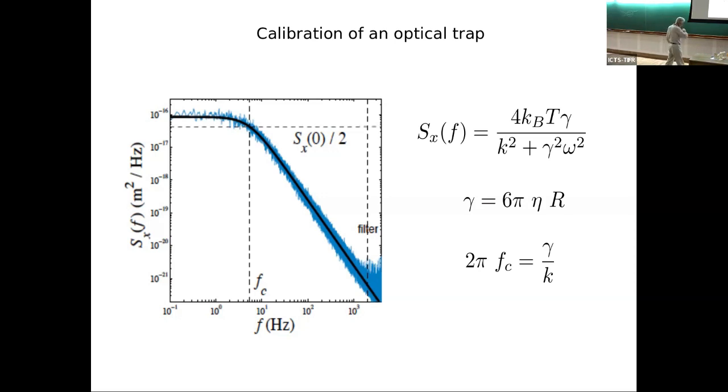This is rather a technical question, but it can be of interest to everybody. We will see in the case of the AFM technique, with the cantilever, the actual noise. Suppose this is what Arne is doing with a position sensitive detector. You start from here, but if I suppress completely the electric noise, then the 1/f noise is like this. So the fluctuations are very large with respect to the 1/f noise. That is the reason why you don't see it.